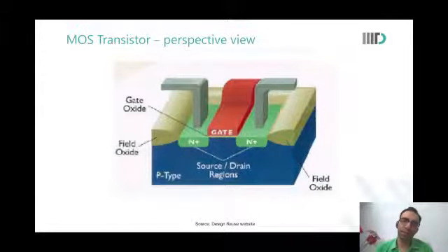Okay. Sir, are there any other capacitances here? Wherever there is a change in medium, sir, whenever there is a change in medium, then we would have some capacitance over there. Okay. So contact and gate capacitance will also be there. Contact and polysilicon gate. Okay. Yes. Good. What else?